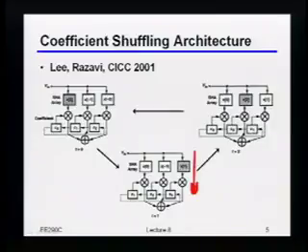Okay, so by the way, just to make sure it's clear, and we'll draw a more detailed example of this in 1 second. Let's say we said that this is good because it gets rid of long chains of sample and holds. But what are you paying for it? What's the trade-off that you have to make to actually get this to work? Okay, that's right. You have more loading on VN. And how does that scale with the number of taps? Linearly? Right. So the more taps you have, the more sample and holds you put directly on that VN node. Right? Anything else that's more complicated now?